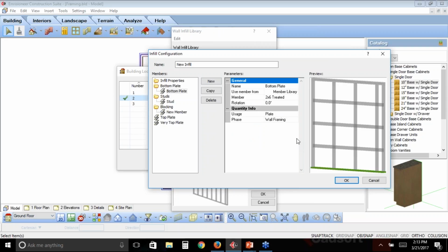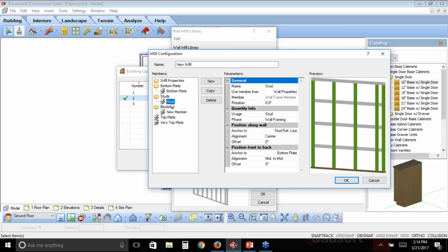So you can frame it always with what's specified in the wall, which is the preferred method. But when you have that time when you need to switch it to something else, like a pressure-treated member, you can very specifically choose that one member, that bottom plate, to be the pressure-treated member. The reason we like to point it back to using the member that's specified in the wall is because in your model, you might have a mix of 2x6 walls, 2x4 walls.